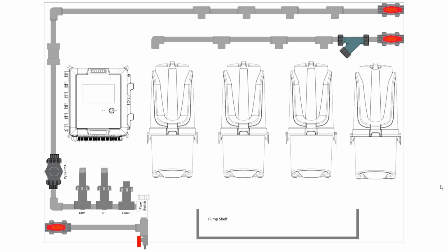The Little Dipper and the Pyxis are used for PTSA. It's a choice. I know that the Turner does not have temperature compensation in it, and it also doesn't have the ability to pick up and mathematically take care of turbidity, whereas the Pyxis was specifically designed around having that. So we have focused a lot more on the Pyxis of late, but it really boils down to preference, the ability to handle the maintenance, and that you're getting the desired results. It's 60-40, which way you want to go and what your organization is comfortable with.